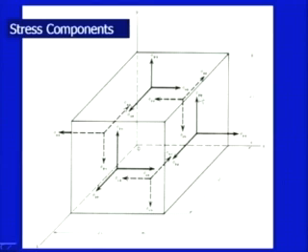But since I have taken the elemental cube, which has symmetry, we need to impose the condition that whatever the stress component is in the xy direction is exactly equal to that in the opposite direction. That means, let us say this is the xx direction, this is the xy direction, and whatever is there in the yx direction, they are identical.